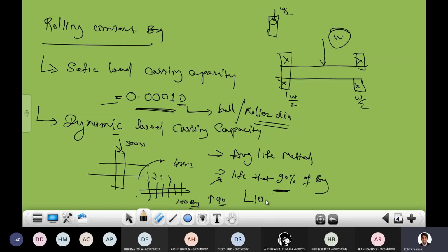ओके, सो वी आर गोइंग टू प्लॉट दी वन ग्राफ रिगार्डिंग दैट एंड विल गेट दी आइडिया व्हाई वी आर टेकिंग दी L10 फॉर द 90% ऑफ द लाइफ ऑफ द बेरिंग। जब भी हम 90% लाइफ ऑफ द बेरिंग के लिए बात करते हैं तो L10, तो ये मेरा मिनिमम रिक्वायरमेंट है टू चेक द डायनेमिक कंडीशंस कि भाई जो भी बेरिंग रहेगा वो मेरा ये क्राइटेरिया सेटिस्फाई करना चाहिए। व्हाट इज दैट क्राइटेरिया, बेरिंग शुड कंप्लीट दियर 90%, जो रूल है मेरा 90% बेरिंग क्राइटेरिया वो सेटिस्फाई होना चाहिए। वो मैंने आपको पहले बोल दिया क्या है, 100 में 90 बेरिंग, आई एम जस्ट टेकिंग अ सिंपल एग्जांपल, आउट ऑफ 100 90 बेरिंग शुड कंप्लीट देयर रिक्वायरमेंट सक्सेसफुली विदाउट एनी एविडेंस ऑफ द फेलियर, दैट्स ऑल। एक भी एविडेंस नहीं रहना चाहिए फेलियर का, कुछ रहेगा तो हम लोग उसको रिजेक्ट कर देने वाले।